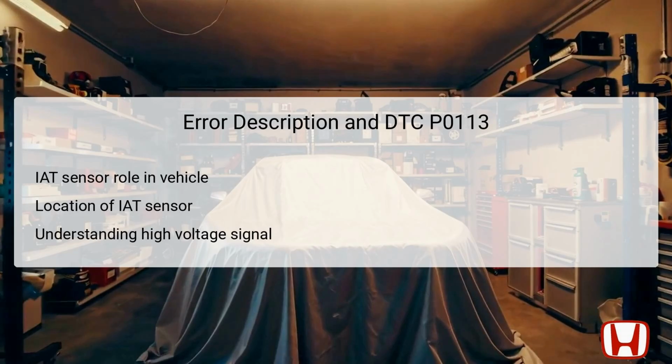When the DTC P0113 is triggered, it suggests that the voltage occurring at the IAT sensor is above the expected range, specifically exceeding 4.92 volts. This high voltage signal can mislead the ECM, potentially causing rich or lean fuel mixtures, impacting engine response and efficiency. Properly diagnosing this code is crucial to ensure that the vehicle maintains its performance standards and adheres to emissions regulations.